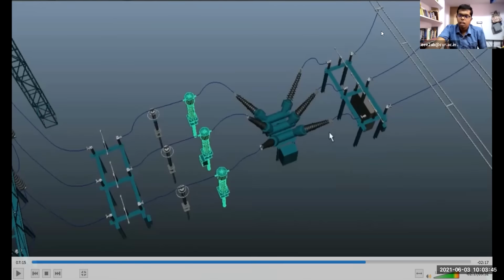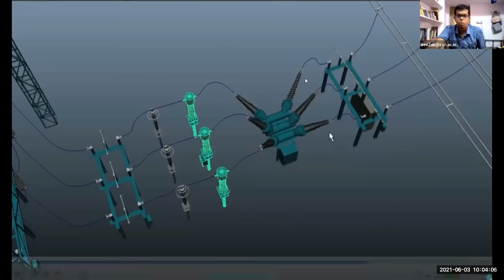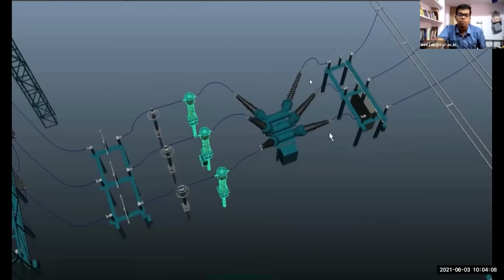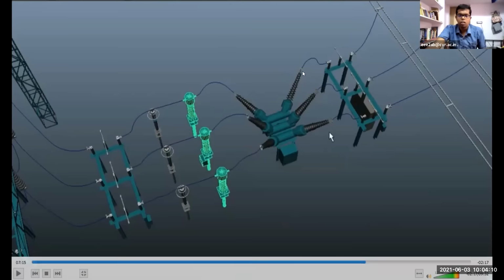he has to ensure that in the part where he is working, this line is at zero potential, meaning the incoming supply from the bus is not coming. So they have to ensure this. The better thing is to isolate both the isolators, and then he can come over here and do the maintenance operation. That will be well and good for his safety.